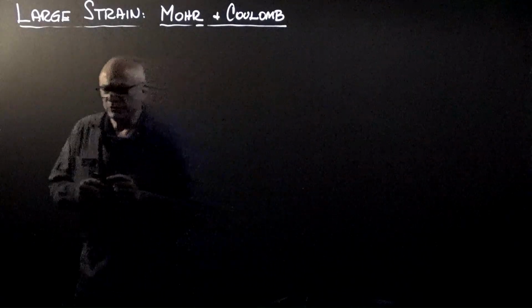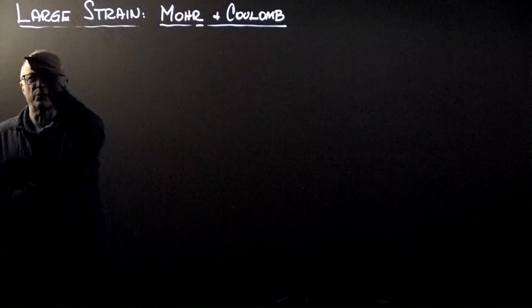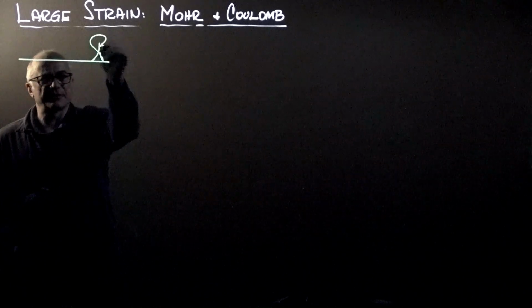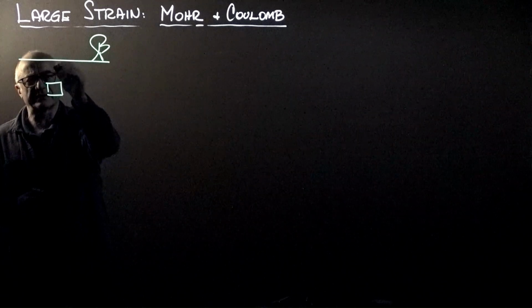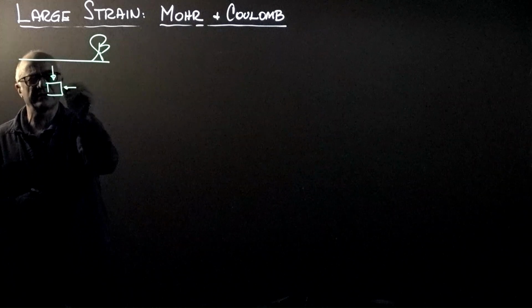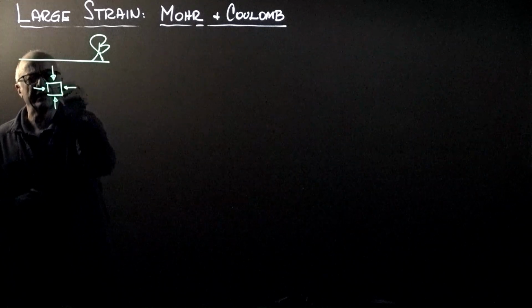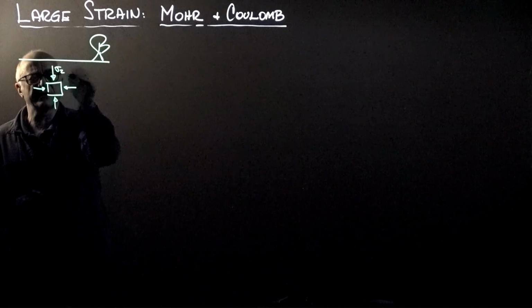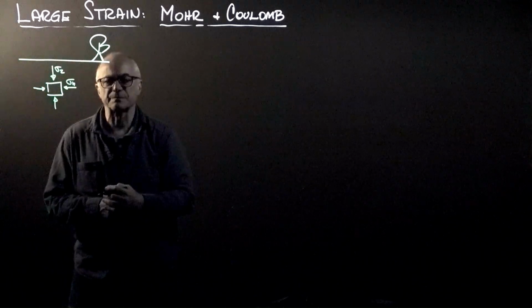Now we are ready to do some stress paths. We're going to consider the following situation. We are in the subsurface, starting from a condition of K0 state. So sigma z is greater than sigma horizontal if it is virgin loading. This is sigma z, and this is sigma horizontal, smaller than sigma z.